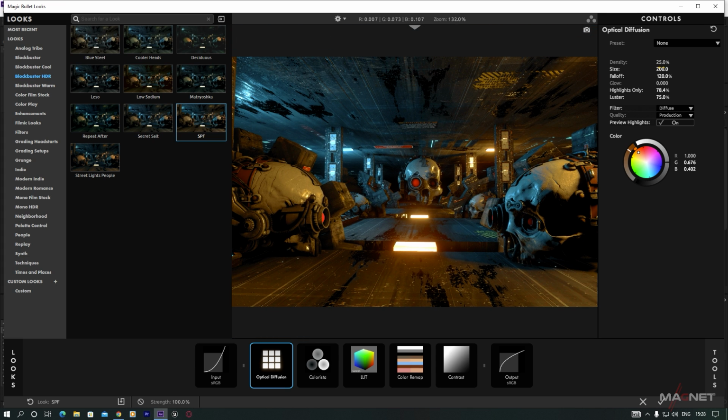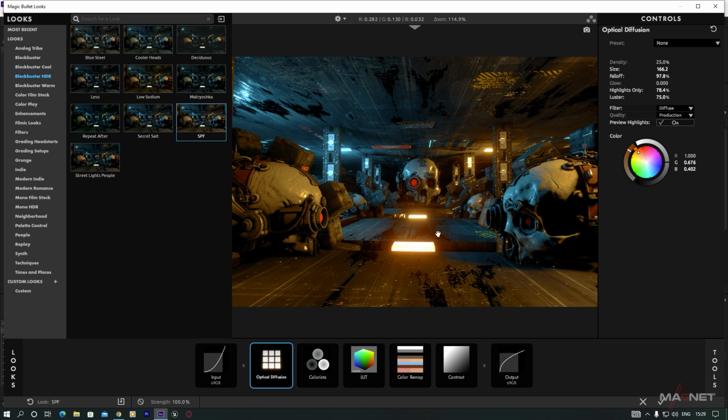Okay, and also we go to this falloff option, and if you increase this, you will see the falloff, and if you decrease this, you will get a very diffuse light over here. Sometimes it looks nice, but for now I make tight settings here to the lights, just like this. Okay, and also we decrease the size. Okay, so this looks really amazing.